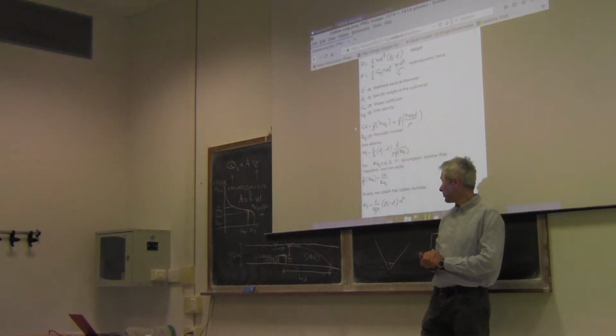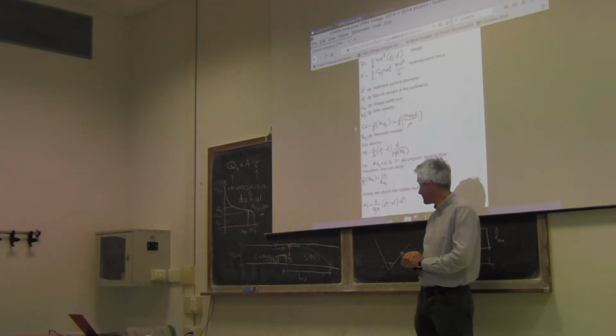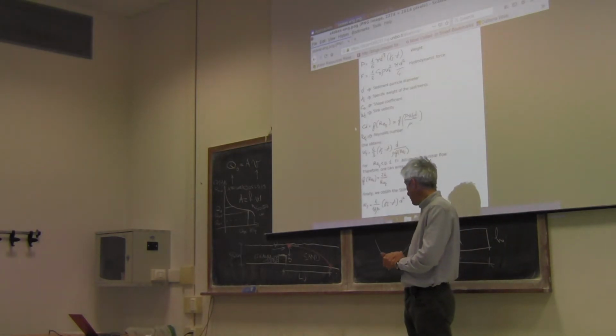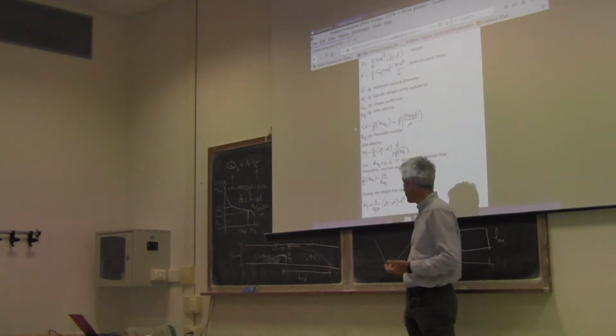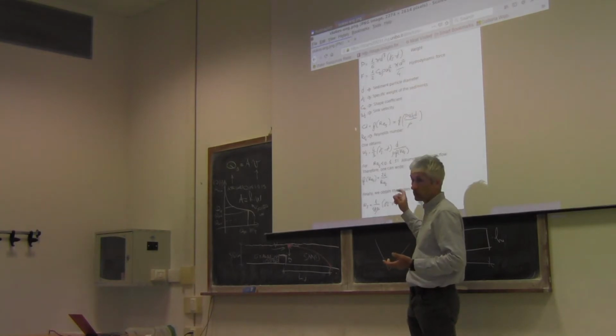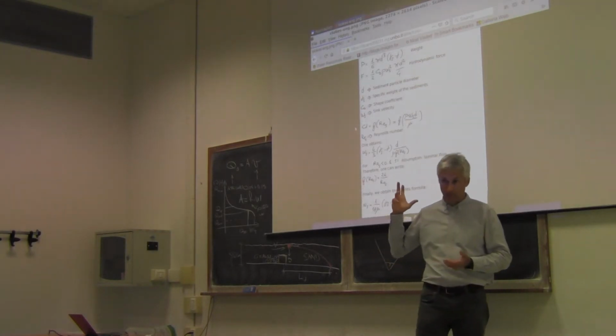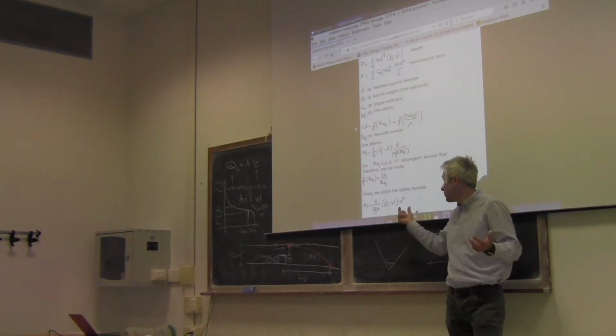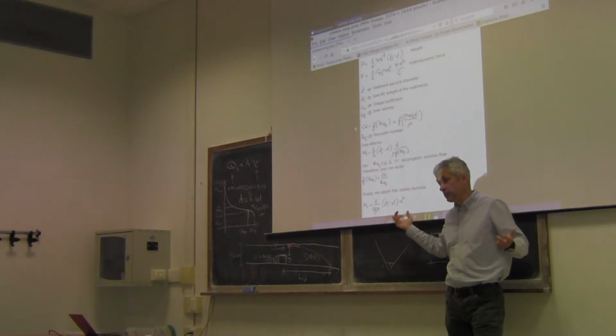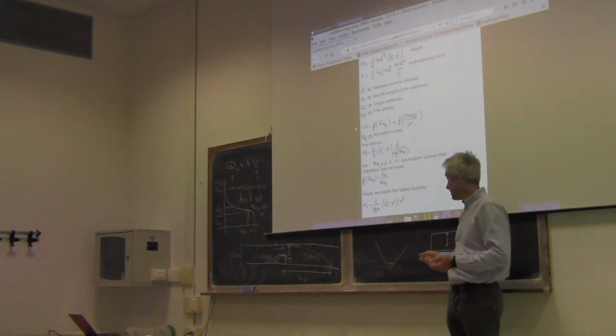What is important for us now to notice is that the velocity, which is called Ws, along the vertical direction, depends on the diameter of the particle squared. Which means that, of course, if we want to minimize the diameter of the sand, velocity decreases.